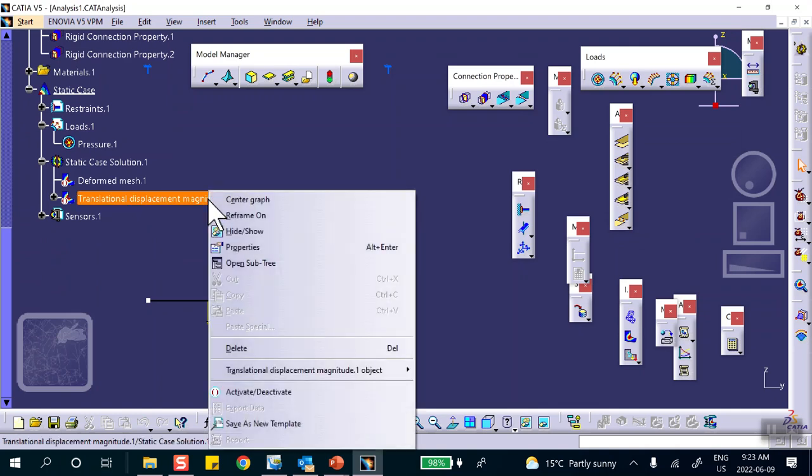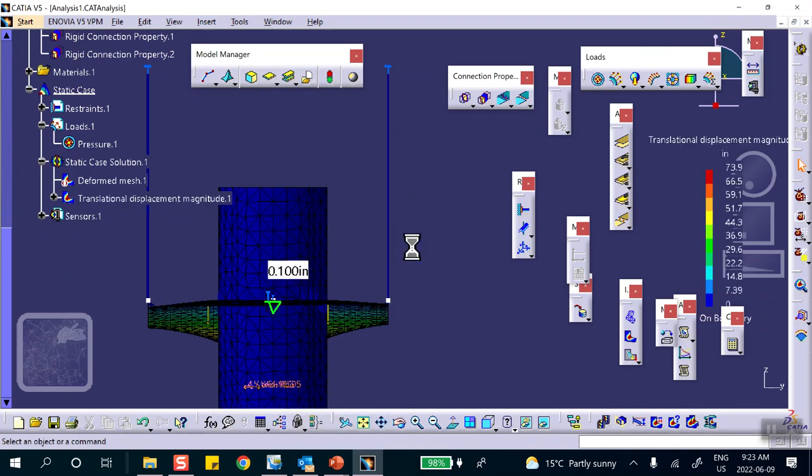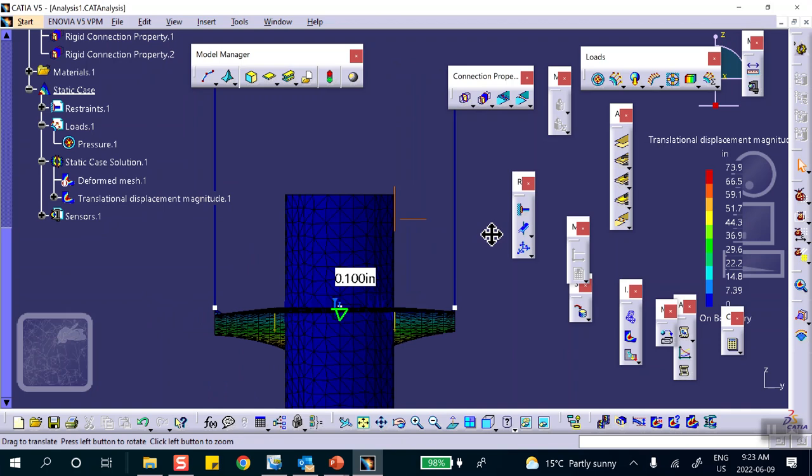Okay, right click, activate. There we are. Front view. The beam is acting as a cable, just stretches. And if you say, well, why is it not actually changing color, the beam? First of all, garbage, 72 inches. Look at the deflection, 72 inches. You put the weight of a car on that little 5-inch by 10-inch sheet, which is 2 millimeters thick. So garbage, I understand that.